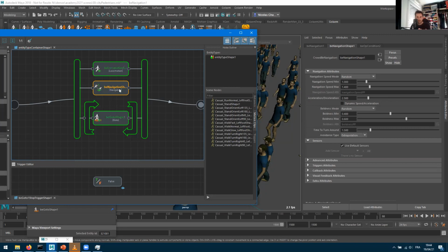But you can use other behaviors to feed that speed and that orientation yourself, and the locomotion will follow it the same way. If you use Maya fields and particles, and you drive your particles the way you want, you write expressions or whatever, the particles will have a speed and a velocity, so the locomotion will also be able to follow those properly. So that's great, right? You provide a rule and the system figures by itself which motion it should play.